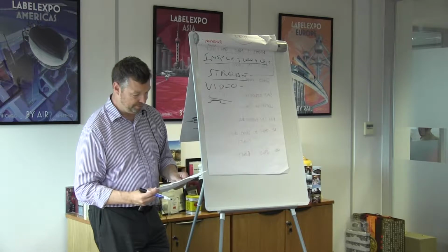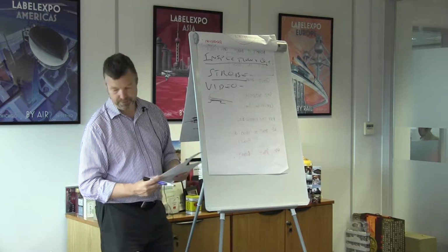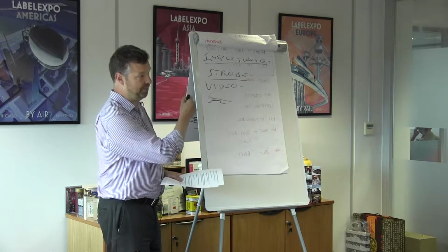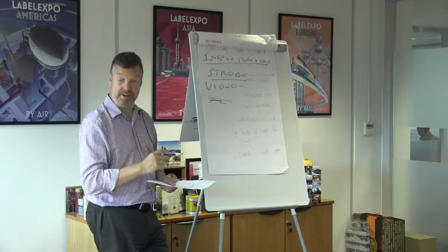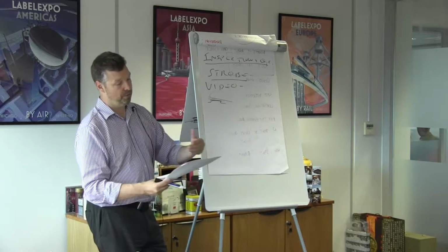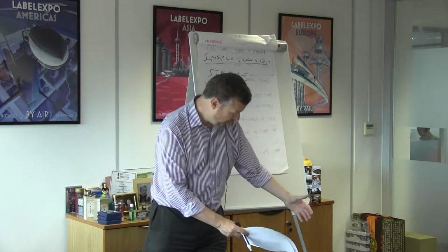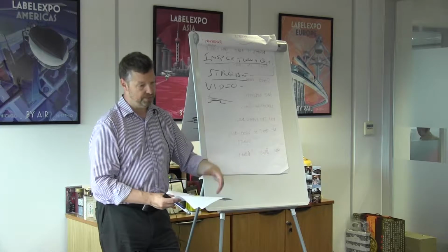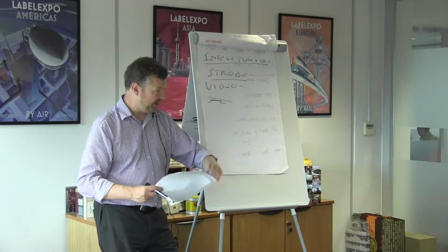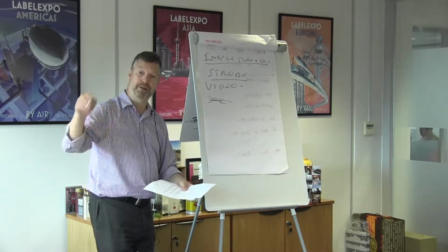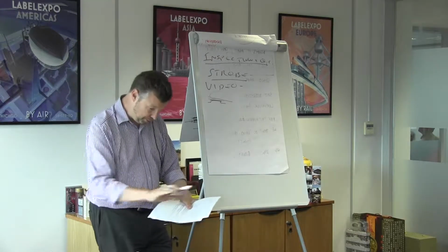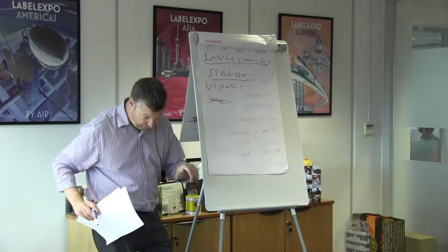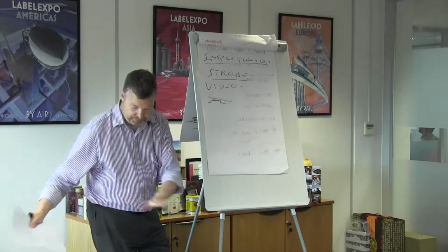Right, okay, so on the rewinder, you also have the same camera. So again, you've got your inspection rewinder, sometimes called a sitter inspection rewinder, because what the rewinder does is take your printed roll from the press. So it's been die cut, labels have been die cut out of that. It puts it on the rewinder, then it unwinds it again and it comes across an inspection table, and you'll see the rewinder operator looking at this inspection table.